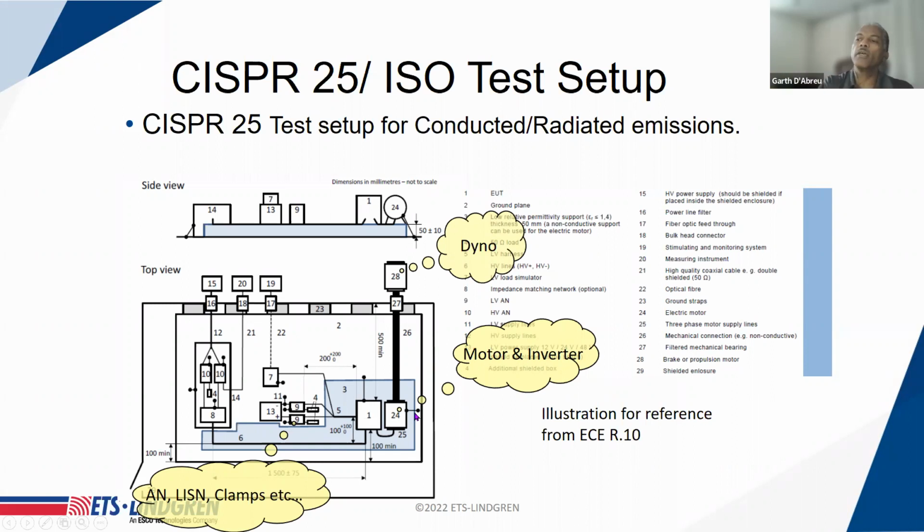Very similar setup. The only addition was this suggested method of loading the motor with an inverter or motor drive, motor dyno, and this dyno could be anything from a water brake to an eddy current dyno to an AC or DC motor, anything that could be used to act as a load for the motor under test, and connected so that it maintains the RF integrity of the environment. Again, in essence, it can be used for this type of setup.